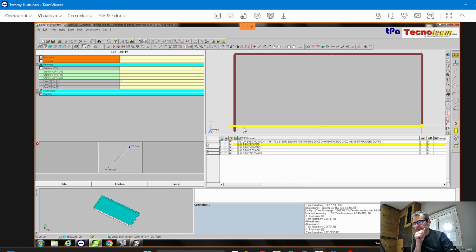But if I start the program this way, I will see something like this. In this place, in this part, and this, so you have the stops of the machine here. So you will see here and here, the machine touches and doesn't touch the panel. And here we will cut the total amount more of the panel. For example, I take a panel 1010 and 610. So I have 10 millimeters on each side to take out, to route. The complete part will be here and here.